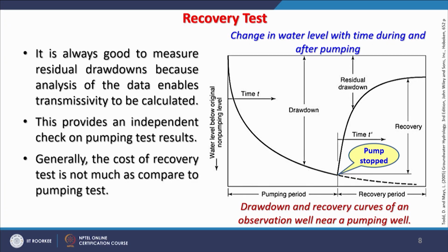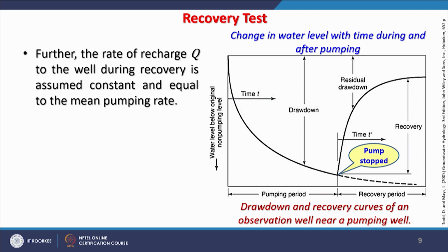transmissibility data. The cost of a recovery test is not much, because it is natural once the pumping has stopped. Therefore, it is always advised that once the pumping has stopped, the readings of water levels and time should continue, so that we can develop this kind of figure which is shown on the right side. Further, the rate Q to the well during recovery is assumed constant and equal to the mean pumping rate.